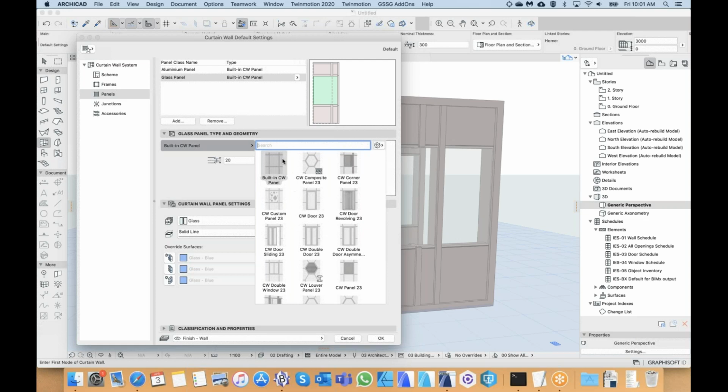In this pop-up for panels, we can see some different shapes. For example, rectangular ones and hexagonal ones. The hexagonal ones purely mean that this panel type will always fit the shape. I'll go through that a little bit later when we start customizing this, but it will fit any shape, but the rectangular ones will always fit only rectangular shapes. So I'll show you how that works.